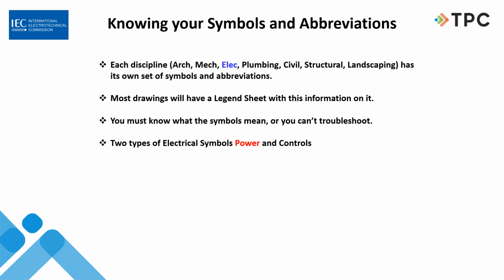Okay. And that's why on the prints, I want to know what the power is. Is that 208? Is that 240? Is that 480? It could even be higher, 4160. It just depends. So that's what those prints help me with and give me a better understanding of where I'm going. They also tell me the equipment and safety procedures I need to use when working on that power. So those are all important.